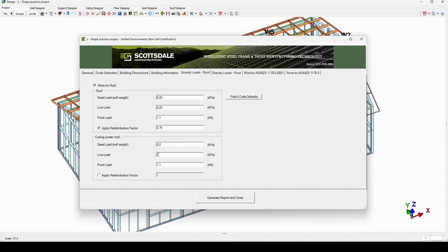Next, we have the live load indication right there. Now, in most cases, you will not be considering a live load as there would not be any indicative load placed right there. If you go to factors like adding ceiling fans or any additional elements, we do have a separate position where you can allocate those loads on separate structures that you would be able to manually control in the design phase.